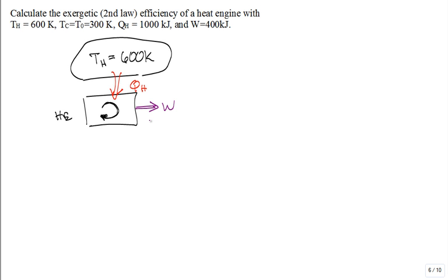But second law, Carnot efficiency, limitations on the conversion of heat into work, you know that you must have a lower temperature thermal reservoir which acts as a sink, and this one is at 300 Kelvin, and you dump off some part of that energy that was transferred in.